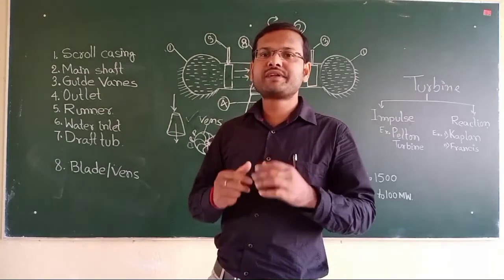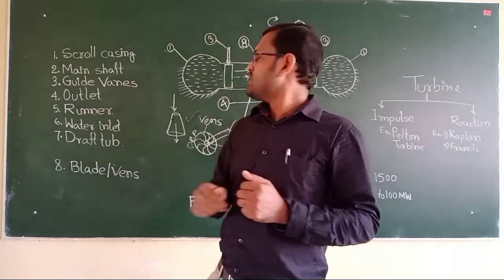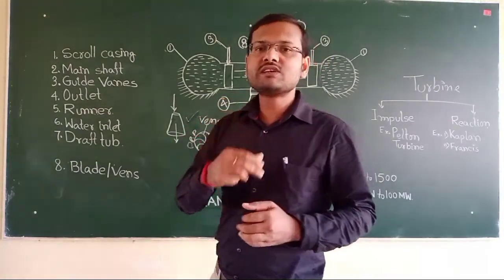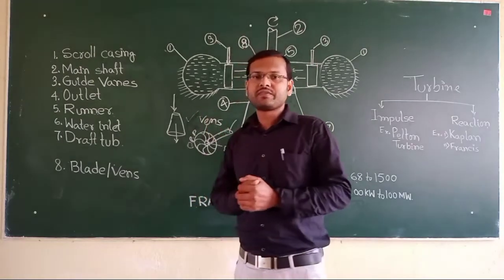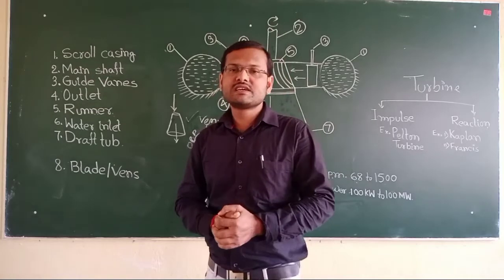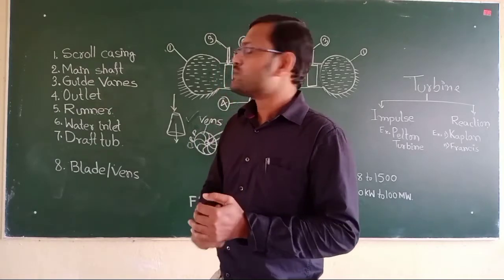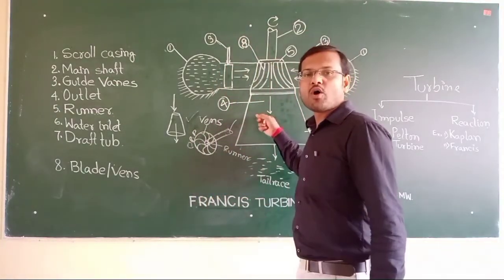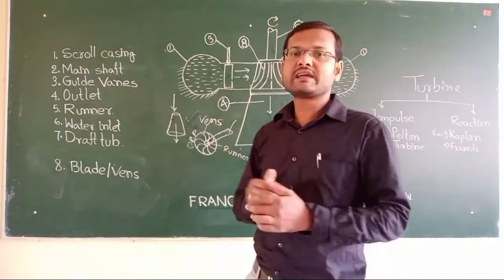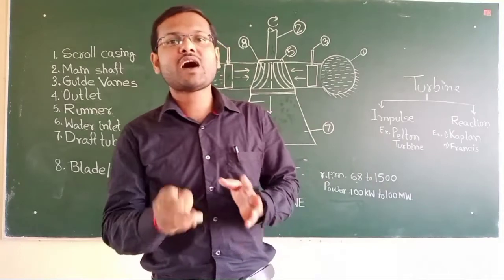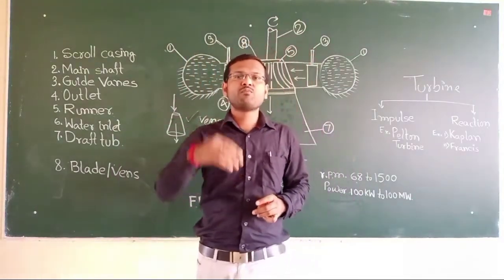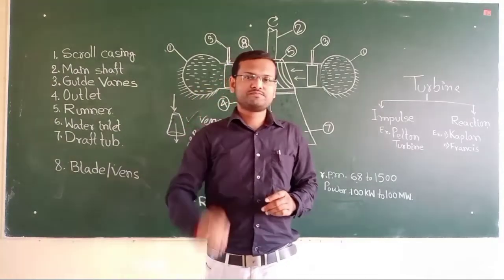The mechanism of the draft tube is to decrease the velocity of discharge water. Therefore, the loss of kinetic energy is less. So, the sum of pressure energy is converted into mechanical work. Therefore, the efficiency of the turbine can be higher.